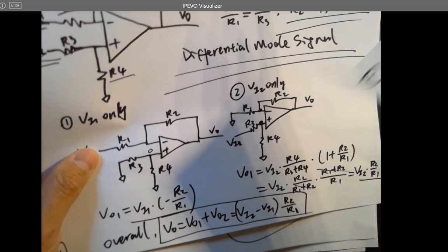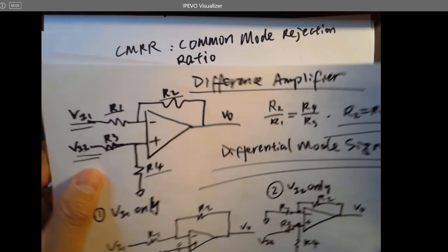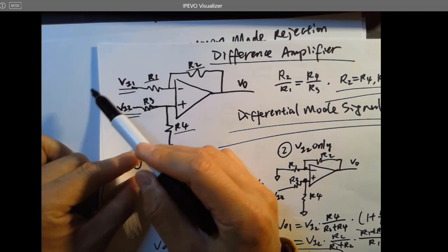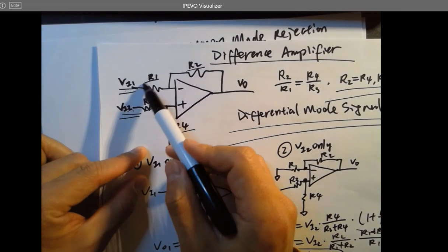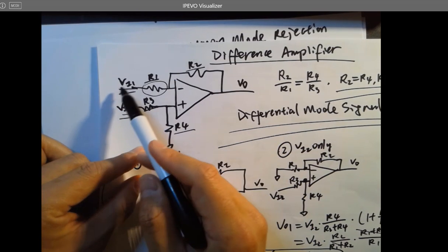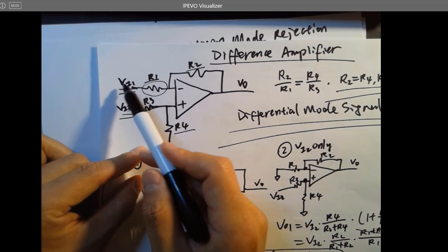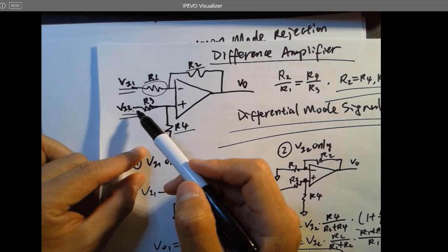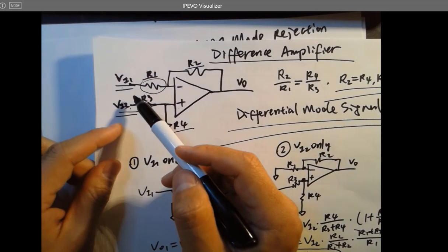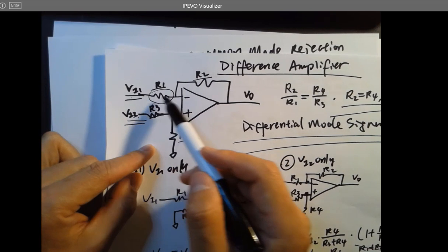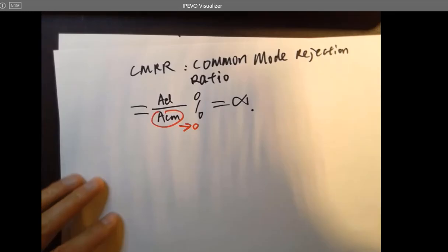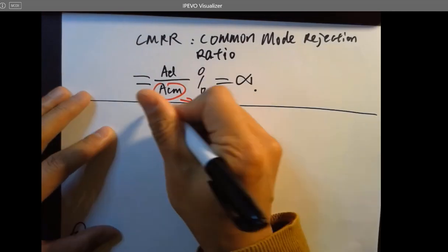So there's a concern over here. If the circuit is directly connected to the two inputs, you have a resistor here directly associated with whatever is in the previous stage. In that case, the voltage can be degraded or affected by this voltage divider effect. So you can use something to isolate it. In that case, we get something very interesting, and the structure is called an instrumentation amplifier.